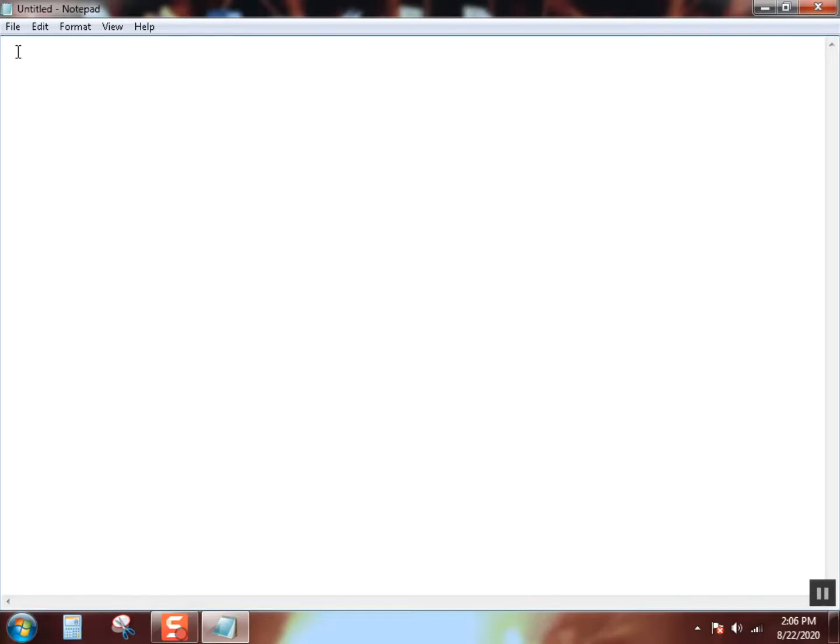First line in any CNC program is going to be a percent sign. So hit the shift key and percent. Then hit enter, new line. Next line is going to be the program name. Program name always starts with the capital O, not a zero. Do not make the mistake. So O, you've already got your caps lock on, and then 4 digits. I'll just go 1, 2, 3, 4. Some will take 5.